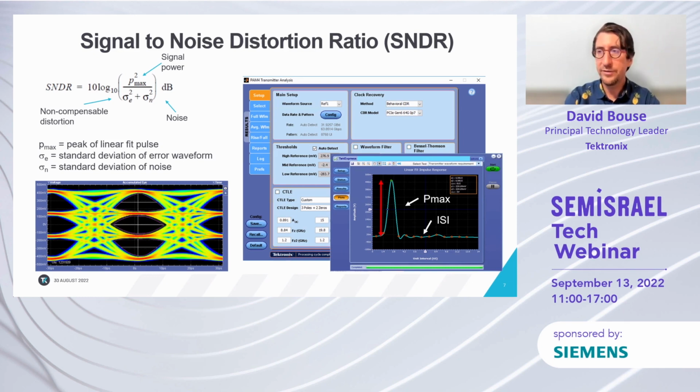And what it is, we're performing clock recovery. We're coming up with the averaged waveform that we capture, and then we're comparing that with a step response recreation of the signal. Any deltas within there become our error term. That error term is what we see as something that's not equalizable by the receiver, and so it's a penalty.